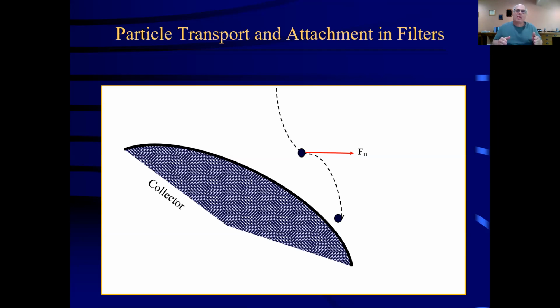So if I make that line bigger by running my filter too fast or loading it too aggressively, then fluid drag is going to become greater because the water is having to move through faster. So that's something that's within my control. As an operator, I can slow that down by putting on more filters if necessary, or at least keep it in a reasonable parameter, either side of speed. I want to make sure that I'm right in the range of speeds that are necessary for running our filters.